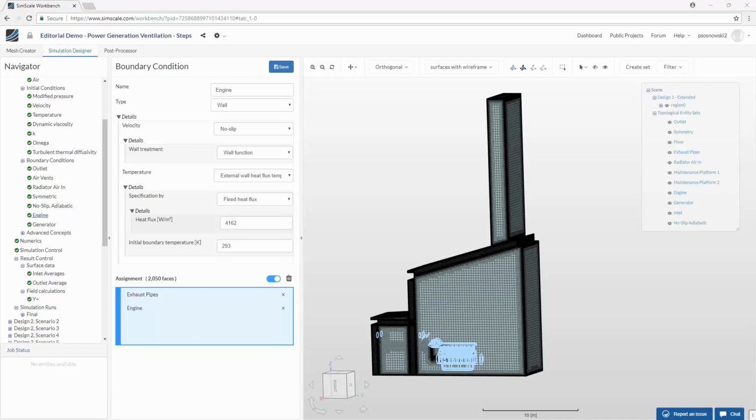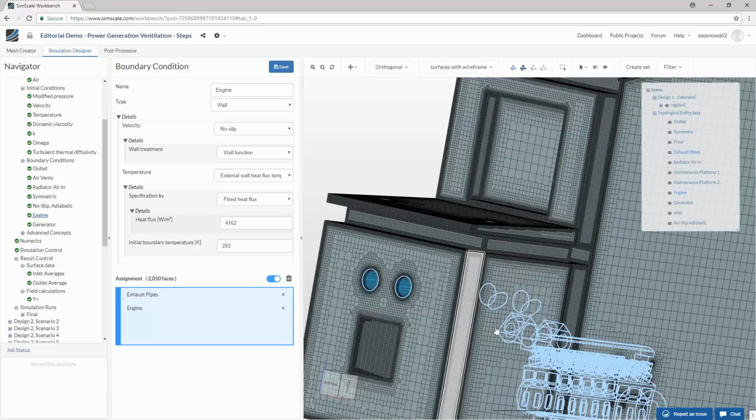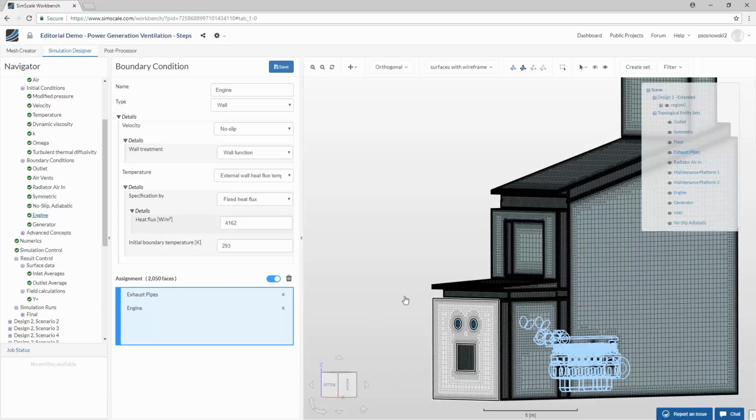Okay, the next question, where does the radiator discharge hot air? In this particular case, we are assuming that it's just being taken out of the facility, I guess through this opening here. So we are not bothered by it at all. It's just taken away. But at the same time, you're raising a very good question: what will happen if the hot air enters the radiator? Of course, it will diminish the operating conditions, and the radiator itself will become hotter, which is not being modeled here. This is why we are modeling the temperature that goes into the radiator. If it is too high, we immediately know that the system will not operate at optimal conditions. And we could set some more restrictions on what is happening within the flow to account for this feature. But in this case, it's just taking it away.